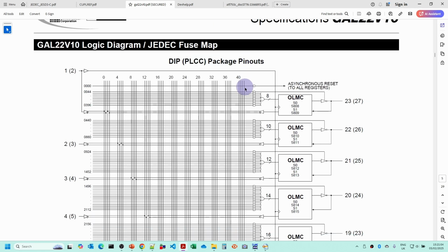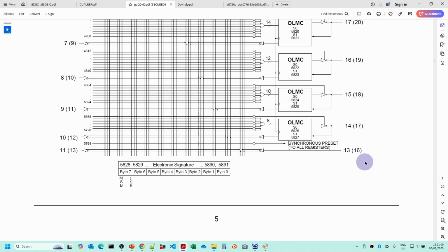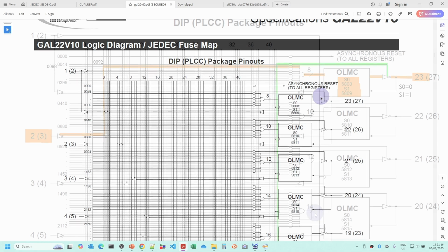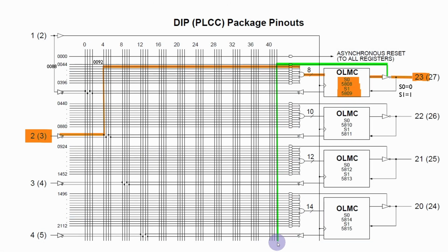So in fact, that junction here is the pin 13 output enable with reverse polarity logic setting output enable. So this just shows that the negative polarity input from the pin 13 output enable, because we had the exclamation mark and it defined, is actually coming up, joining to here, which will be 87, and then we're doing the output enable there.